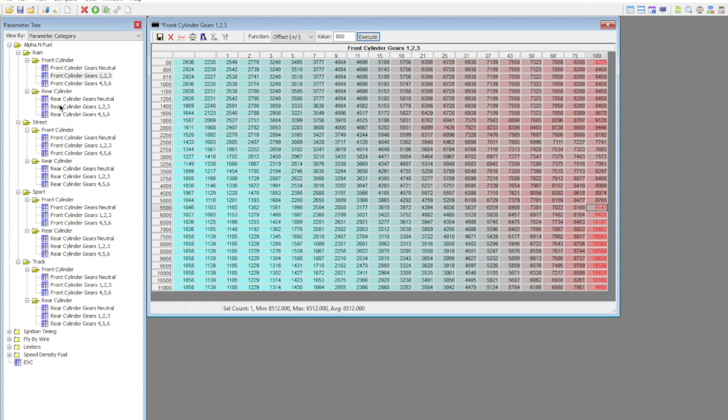And that's the key of making power on any V-twin. Your front and rear cylinders, any Harley tuner knows this, are mapped completely differently. The front cylinder often runs cooler because it has air directly going past it. The rear cylinder runs hotter because it's more physically constricted. As a result, the front cylinder usually runs a little bit leaner, rear cylinder runs a little bit richer, and therefore you can extract more power by kind of equalizing them, within reason, of course.